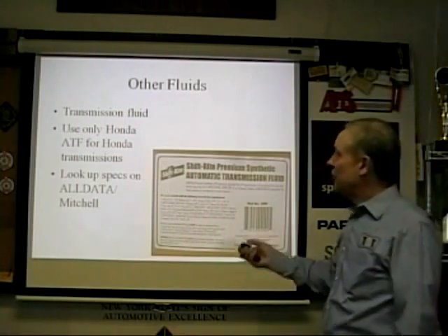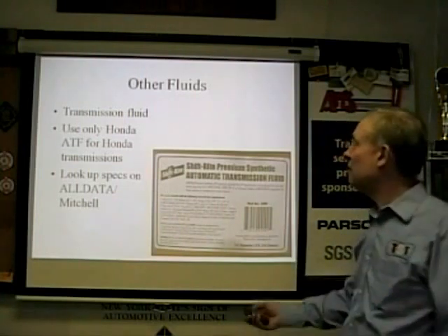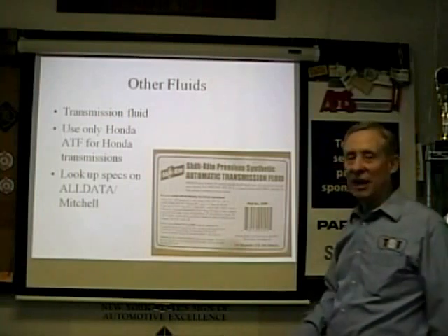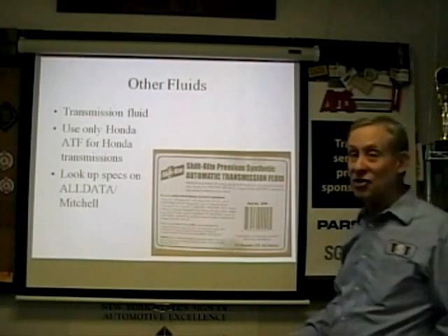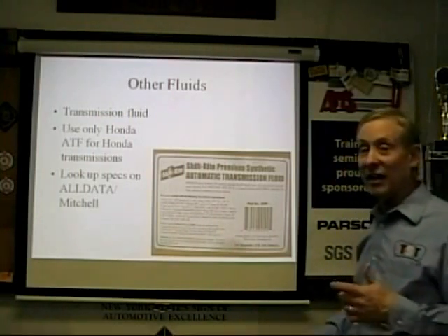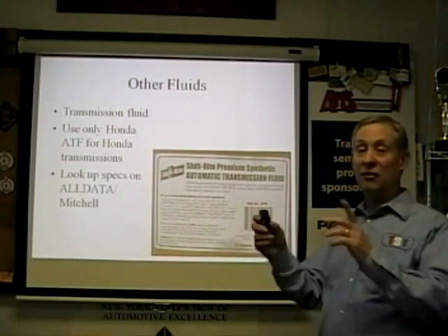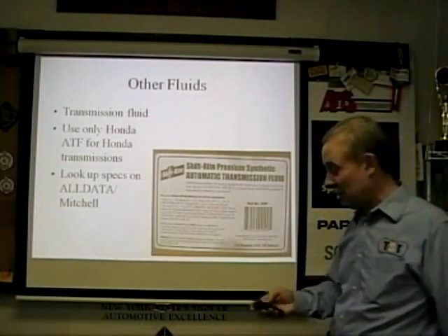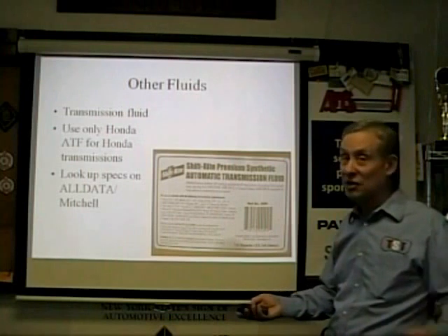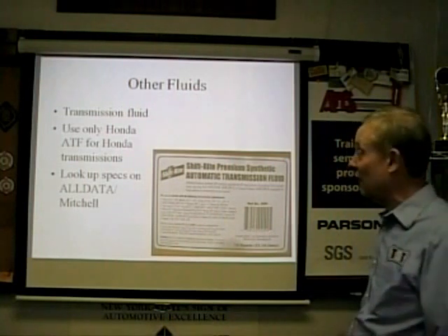Use only Honda ATF for Honda. Look up the specs and all data in Mitchell, or if you have factory information, you can go to nastf.org and get the factory links to all the factory websites, and you can get all the specs from the factories. They have a lot of stuff published.